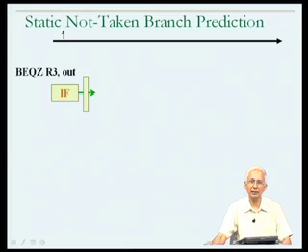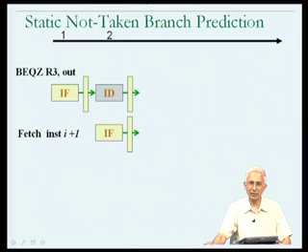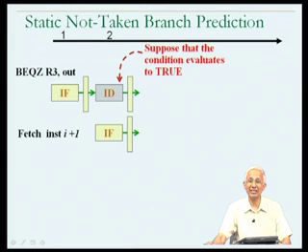In the other possibility, as before, the instruction is fetched in cycle 1, in cycle 2 the instruction is decoded, and once again I am building the hardware to assume that the branch is not taken. However, by the end of that cycle I determine that the condition is in fact true. Unfortunately, the condition is true.